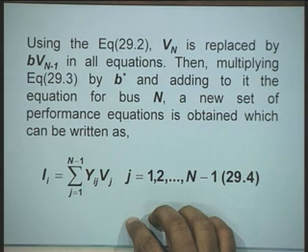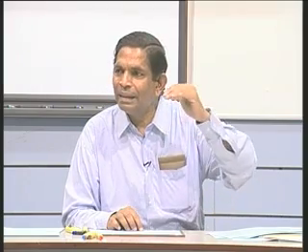That is, when I have done this reduction process, the voltage of n minus 1th bus was retained, right. But suppose you have, instead of two machines, say 4 or 5 machines which form a coherent group, then you can select one of the machine buses and retain that bus and its voltage, right. So now we can say that we have a network where an equivalent machine is connected to the bus which is retained, and for the equivalent machine we have to find out what will be the parameters of that equivalent machine.